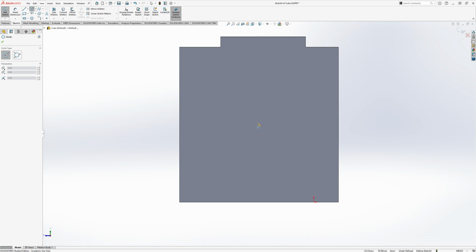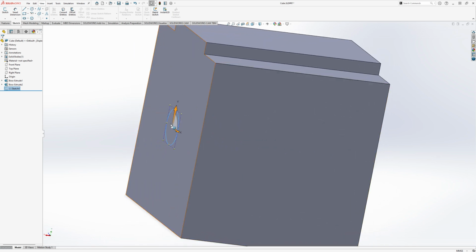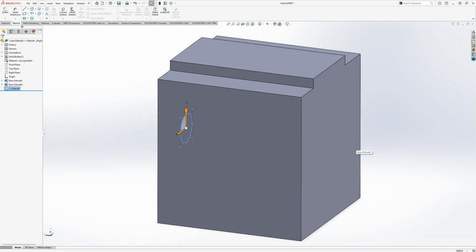So I'm going to click wherever you want, and as you see from the center it's drawing out, and click anywhere, it doesn't really matter, and we're going to define our radius as 10, with the diameter being 20. Press enter, and this now has a radius of 10 and diameter of 20, as you can see with that line. Now the sketch is done. I want a hole, a round circular hole going all the way through, coming out the other end, so this is technically hollow.